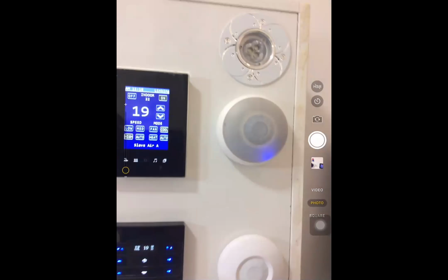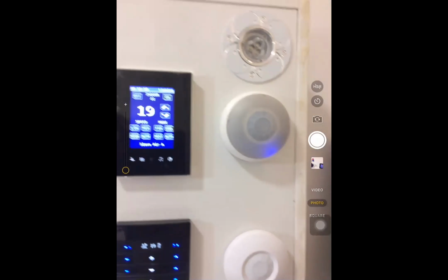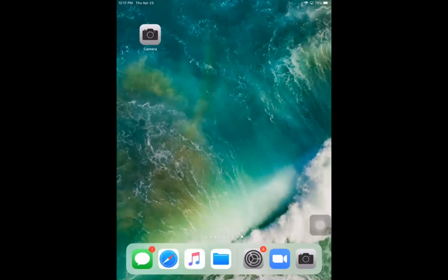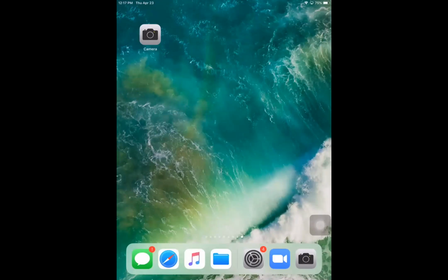Therefore, you can even put the Luna as a master and another panel such as bedside and theater as a slave. You can do it like that. Remember, never program one AC on two panels. Always use a master and a slave. Question?